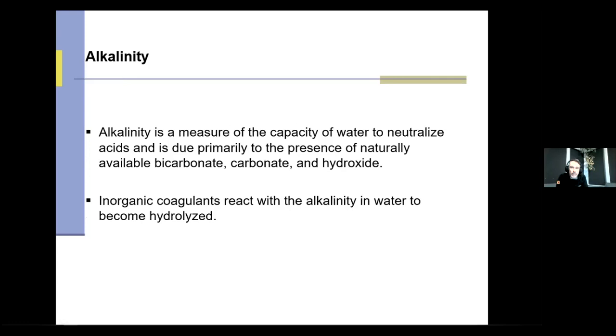The inorganic coagulant, the cationic coagulant in this case, reacts with that alkalinity. We saw that, right? Those OHs in the water on those 6 arms, and once all 6 arms are full of alkalinity, that thing's ready to go. This is called hydrolyzed. So once a coagulant is hydrolyzed, that means the alkalinity from the water is bonded, it's ready to go. It's a strong bond and it will start working for you. It's perfect. But it needs that alkalinity, right?